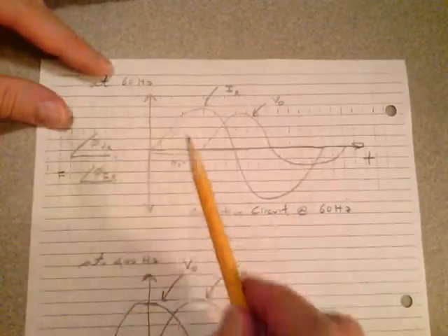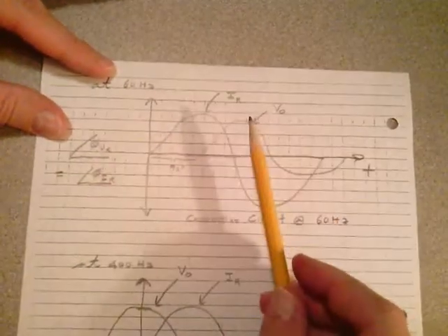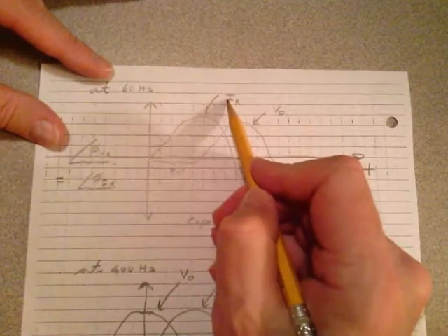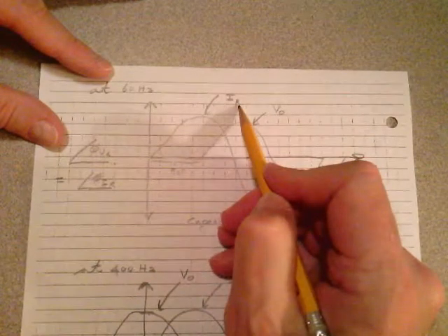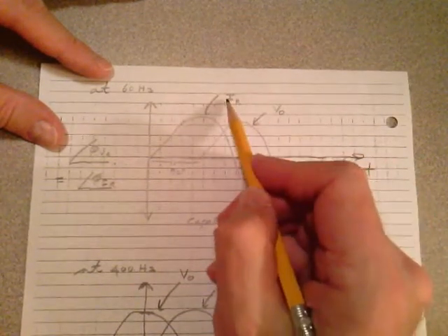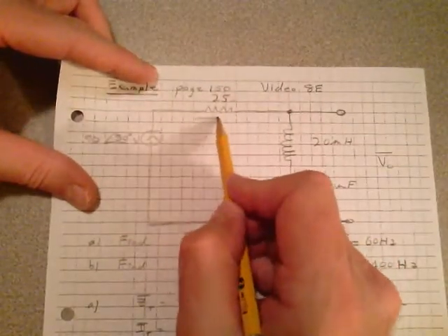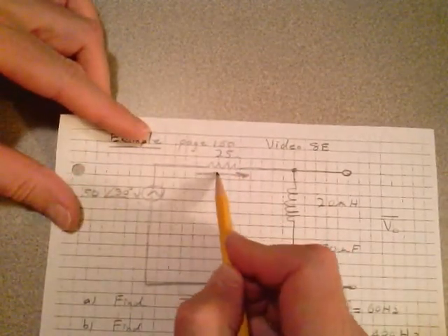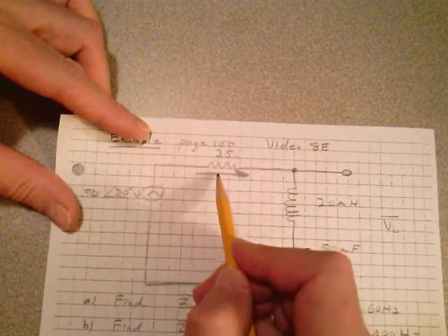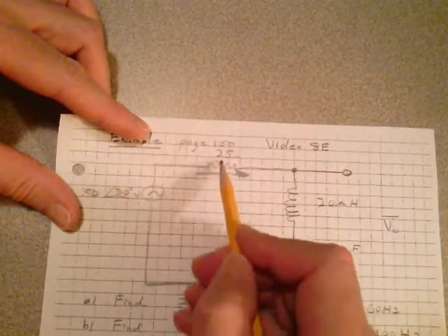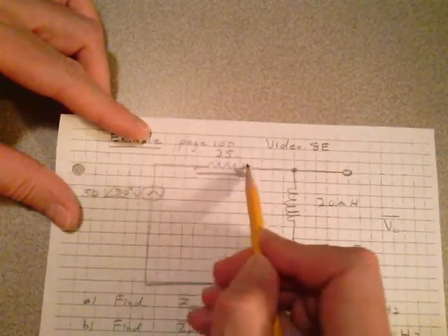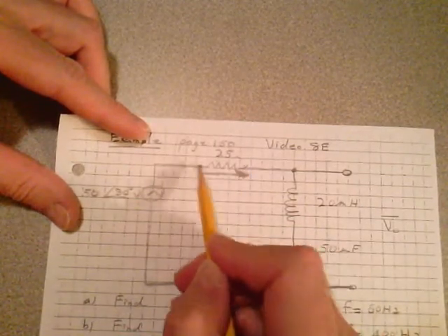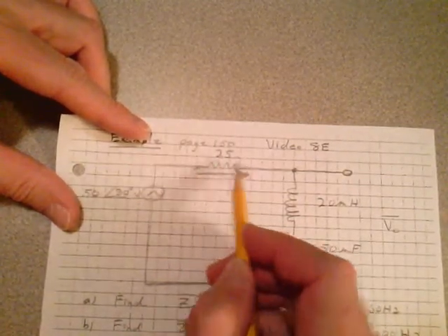Now, what I did was, at 60 hertz, I took a look at the waveforms, and I said, let me use the current waveform as a reference. If we look at the current waveform as a reference, all we'd have to do is realize that the current goes through that resistor right there. Now stay with me, this is important. That current flows through that resistor, and through a pure resistor we know the voltage is directly in phase with that. Just between this point and this point, that current has to be in phase with the voltage across that resistor, because from here to here, it's purely resistive.